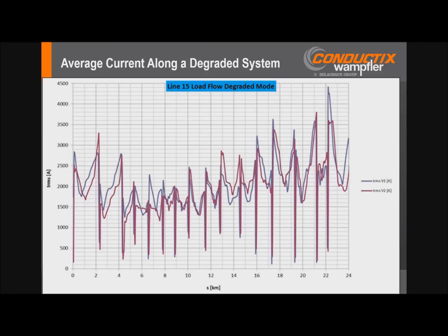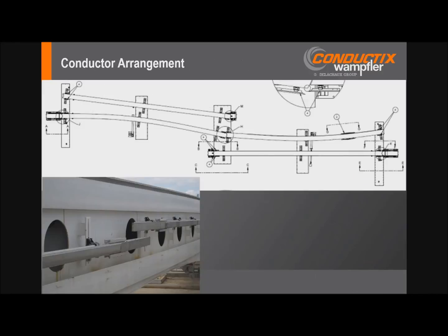Such trade-offs are pretty common in power rail design, and substation location is influenced by a host of factors other than the power rail as well. It's not always easy to locate them between stations, though stations are a logical place to place them. Considering grid connections, space in a built-up environment, and geography will also drive the flexibility of locating substations.